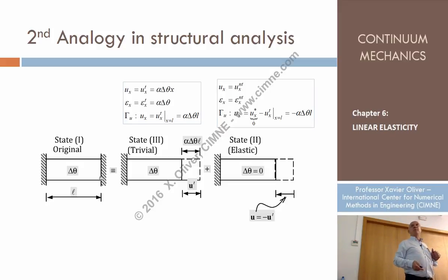But, very important, you are just considering here that you know these thermal displacements. When we say, let the structure expand, that means let's compute the thermal displacements. And this thermal displacement field may not exist.